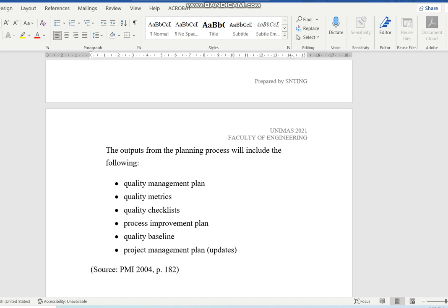And then it will build up into your methods. The method will be the steps. Okay, you excavate first, then you lay your pipes, and then you cover it. For each of these steps, is there anything specific you need to look at or check in order to get through the whole process? Each and every one of these items, you are looking at. So you can use a flow chart to lay out the work method first, and from there specify the material, the machinery, and then the manpower, with all your requirements.